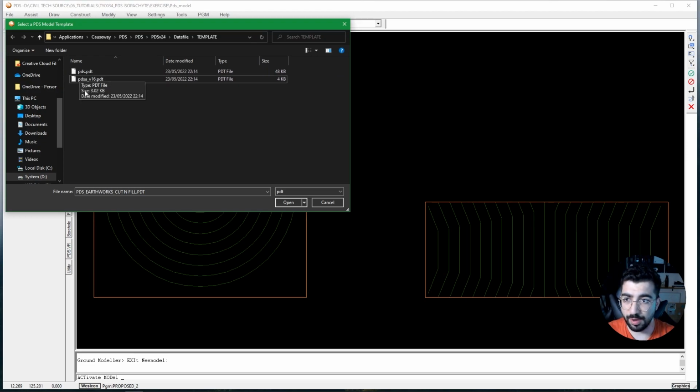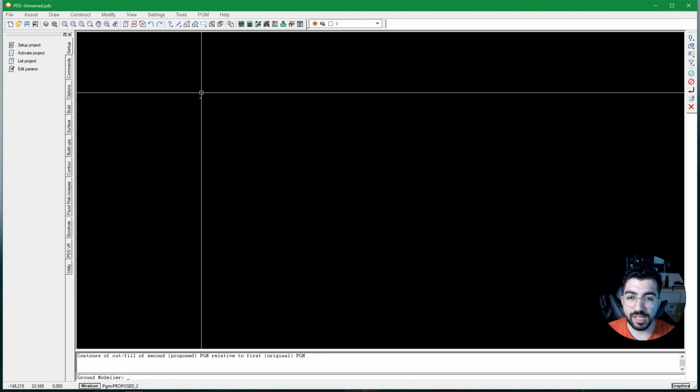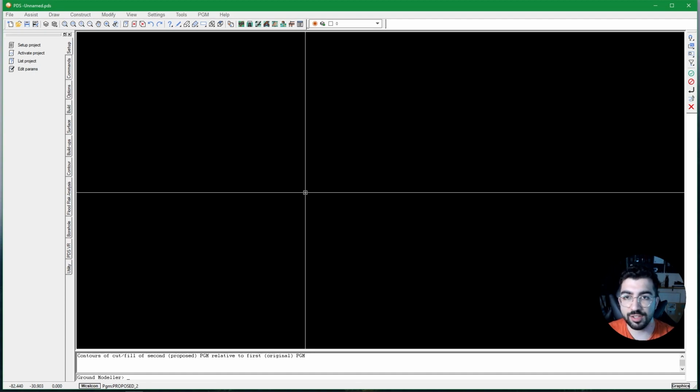These usually appear when you create a new PDS file. So I'm just gonna go PDS only, and that is for version 16. So I'm gonna hit open and just okay. Now, when setting up the PDS template, you need to know a few things. You need to know what depth bands you're gonna do, the layers, colors, all these things.